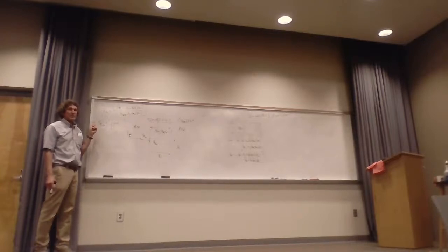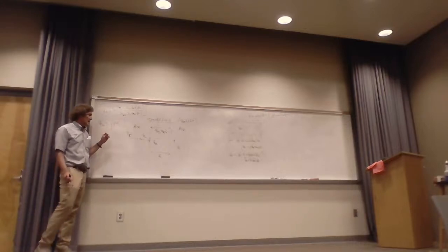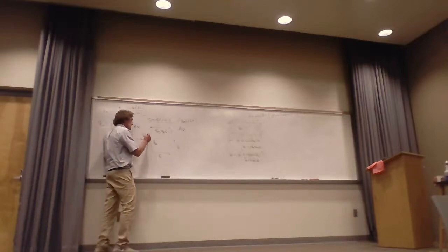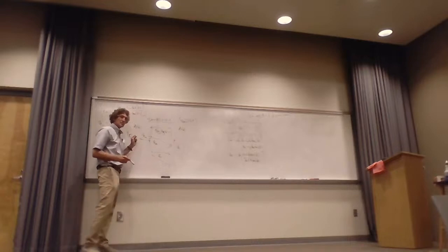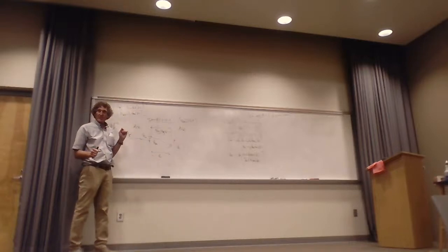if the skin depth is several times L, what actually happens is this. Wave comes in here, a little bit gets in, it hits this surface, and reflects back. Did you have multi-bounces in transmission lines? Remember the bounce diagrams, anybody?